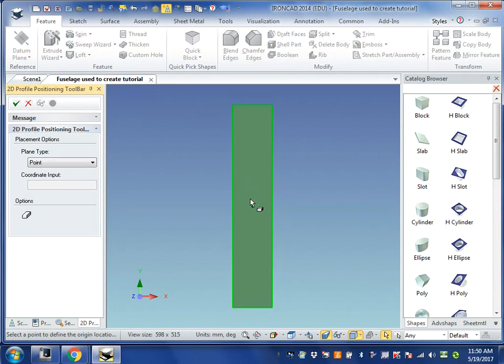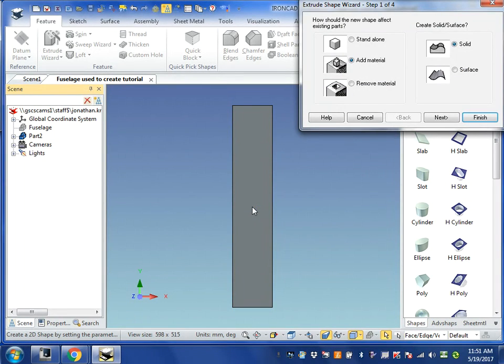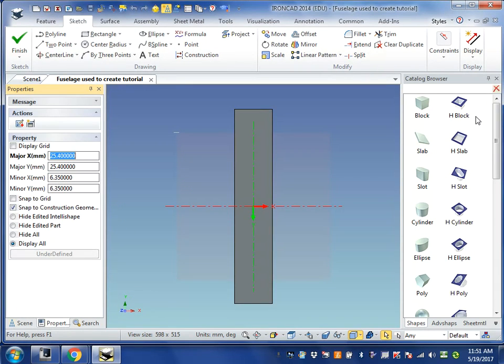This time, guys, when you select the top surface, don't forget, like I did, and I'm going to click in the middle here, aim for the green dot. That way you just make sure you get the right spot. Sometimes people get an edge or something and it causes them problems, and it's not going to work. So we've selected our surface. Now we can do a remove material, and now we're going to, of course, click finish. Okay, so now I'm awake and ready to go.